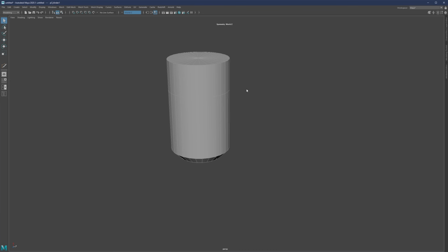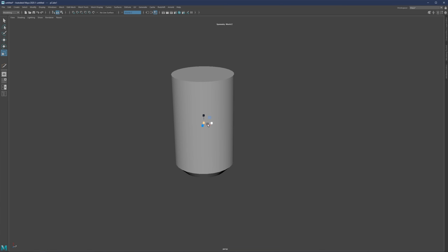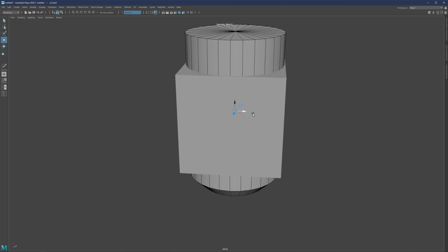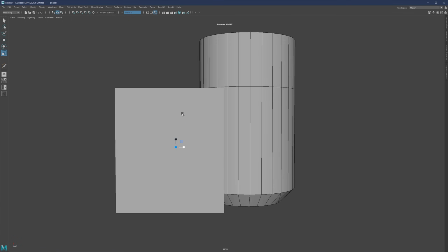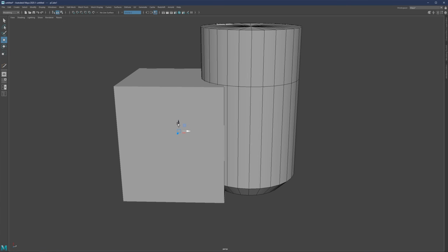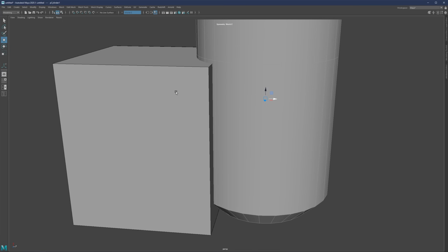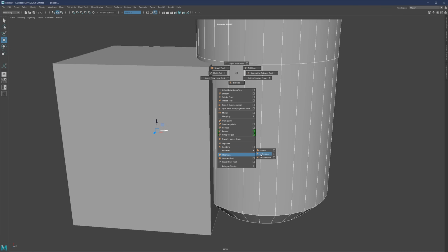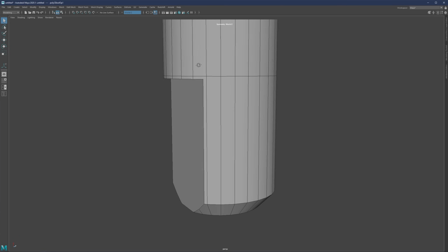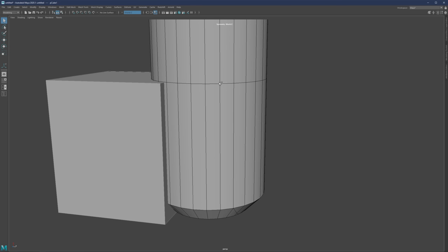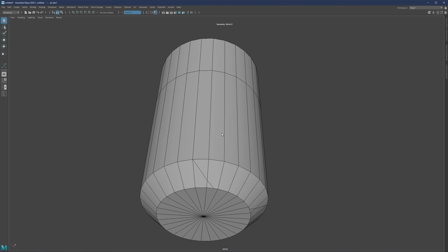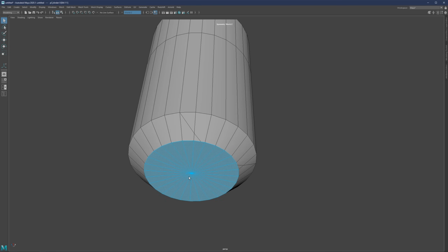The other way would be to go to your object mode and then select the cube. With the cube, you basically need to do the same cut, but you now need to reposition it. So let's say something like here, and if we now do the cuts, we might have some extra geometry to work with. So it's again going to be a balance between the two, depending on what works for you in this case. But I just went for multi-cut. In many situations, I will just go with the multi-cut.